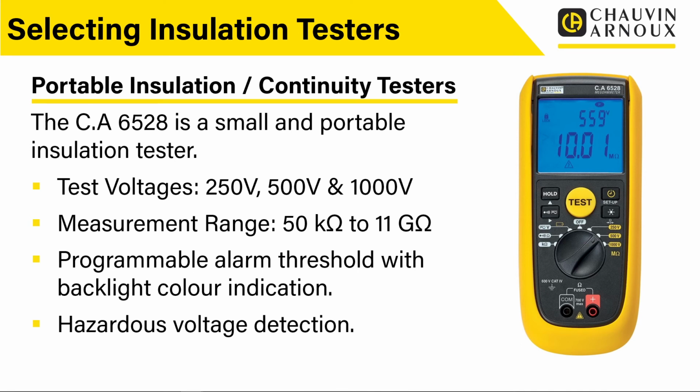It's got a programmable alarm threshold with backlight color indication, so you can actually set at what resistance value you want the backlight to change to red and tell you that it's failed, or that it's lower than you would expect. So it gives you a nice clear indication. If you're testing quite a lot of things in one go, you don't want to be just staring at the screen all the while seeing that going up and down. You can actually hear and you can see that alarm function.